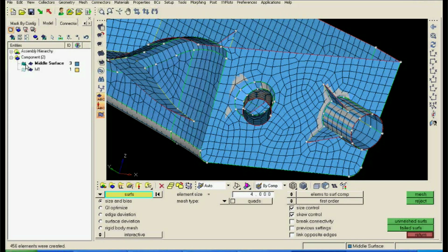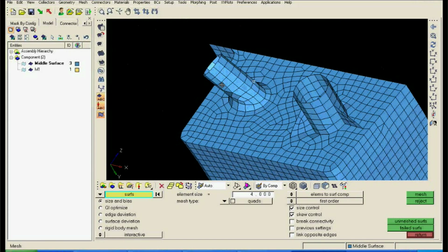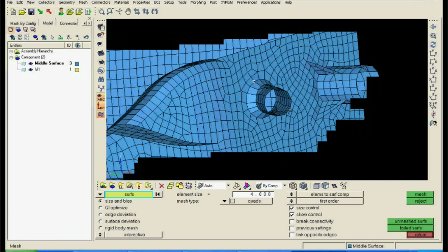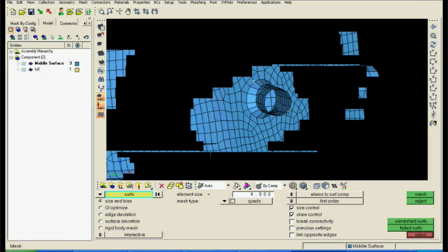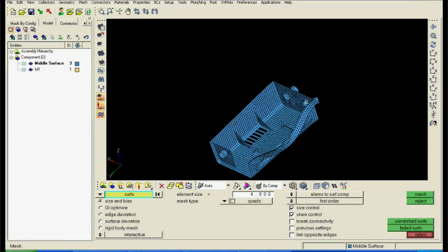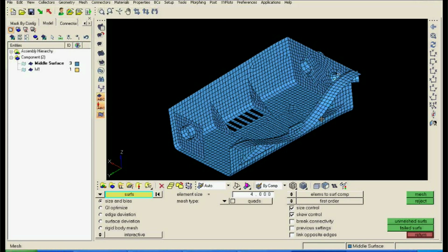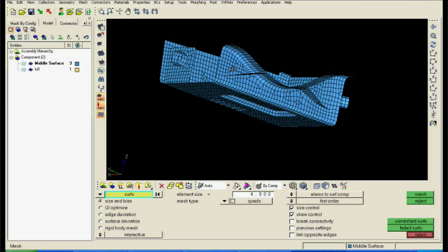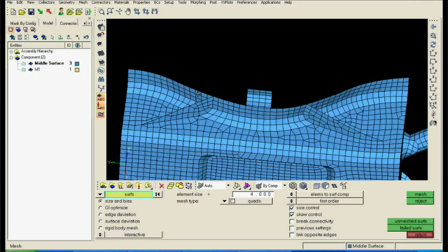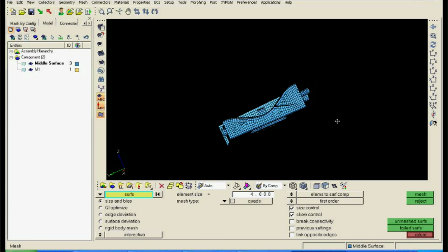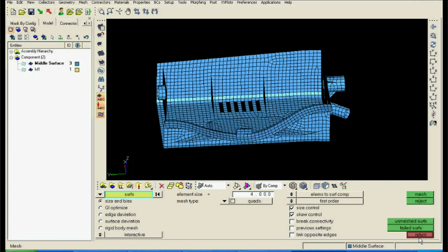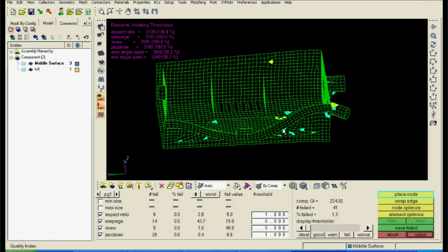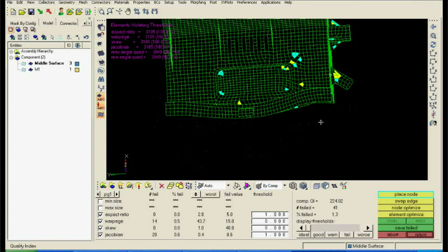So this is now more or less the final model, completely meshed as I would have expected. But let's check out the quality, because I do expect there will be some high quality index and we need to work a lot. So let's check out. So again going back to quality index, and yeah, it's 224. So it's quite high, mainly in this area like such cylinders, and this is what I'm not expecting, such problems. It should be there, and it is there.